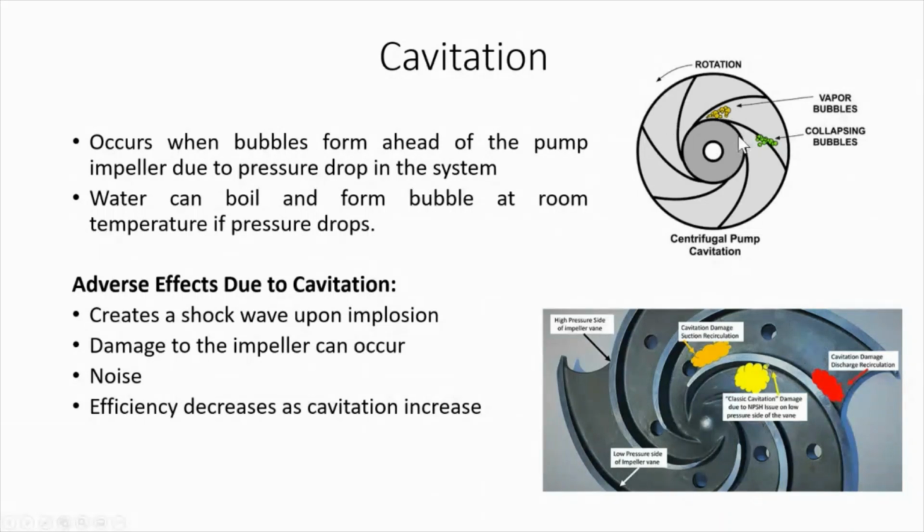Now, these bubbles are filled with air, or steam. So definitely, they don't have as much inertia as a liquid will have. Let's say there are a couple of bubbles in here, and these blades are moving. By the time this blade touches it, the vapor won't be able to move as fast as a liquid. So this blade is going to hit it with all its speed, and those bubbles are going to burst on the blades.